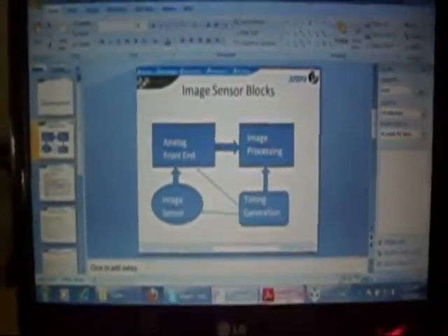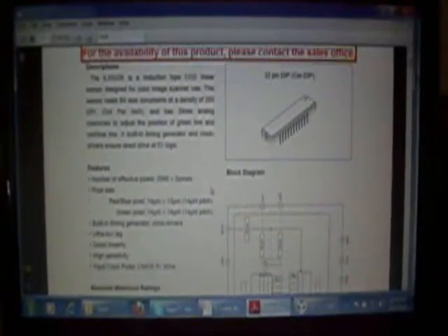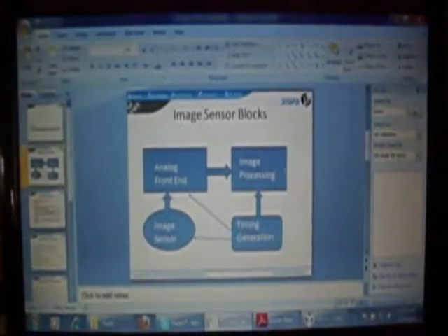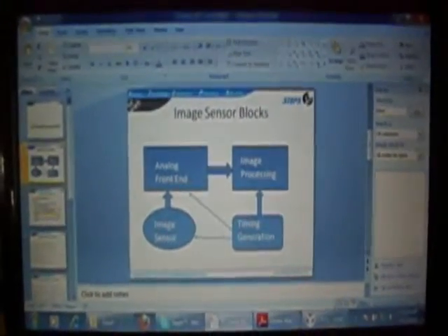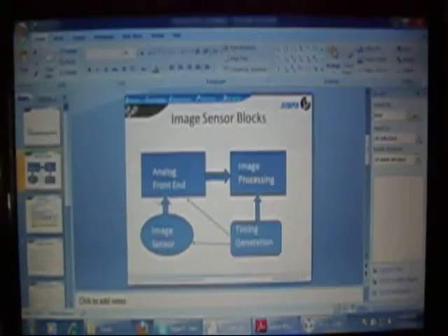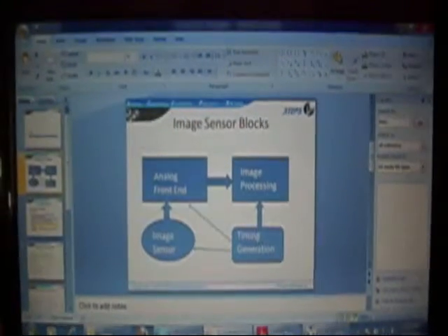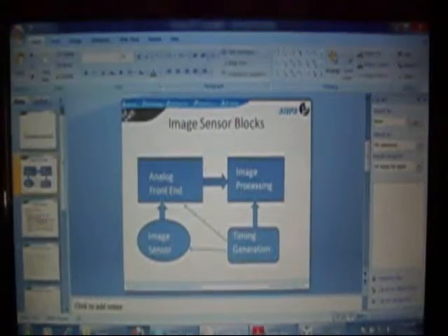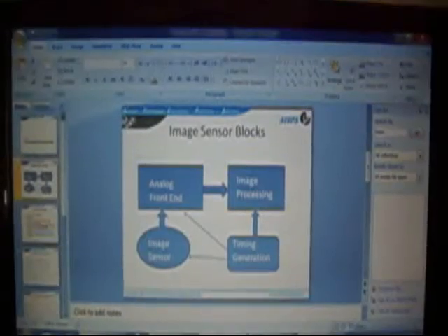Such designs have an FPGA or a DSP for the image processing section, and generally they do have an FPGA or CPLD for the timing generation. They also generally require an analog front-end system to properly interface the CCD analog signal to the image processing blocks. The applications of this project are all machine-vision based applications.